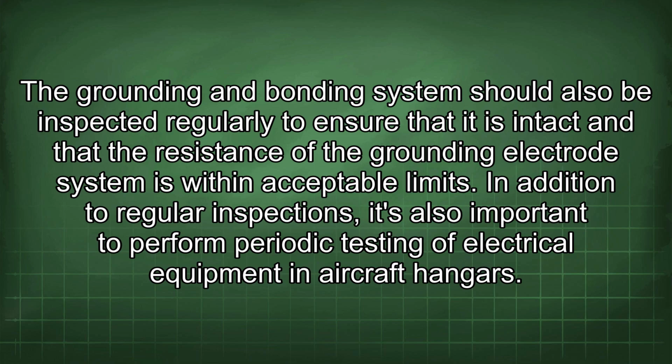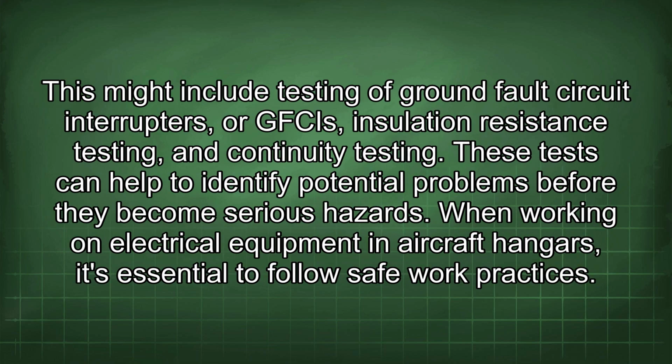In addition to regular inspections, it's also important to perform periodic testing of electrical equipment in aircraft hangars. This might include testing of ground fault circuit interrupters, or GFCIs, insulation resistance testing, and continuity testing. These tests can help to identify potential problems before they become serious hazards.